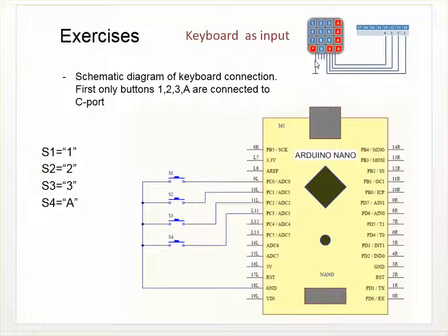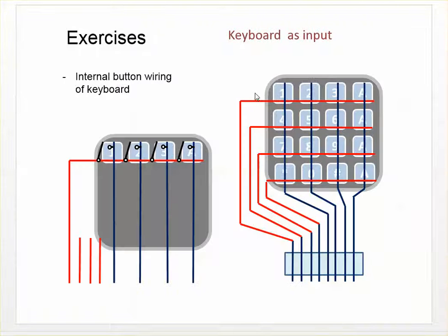So we can control the P port so that we put this line, for example, to 0, and if the other lines are logical 1, then we have this kind of situation: this one line is grounded and the other horizontal lines are in logical 1. So these red lines are now controlled by the P port.